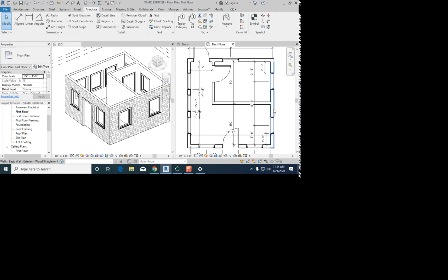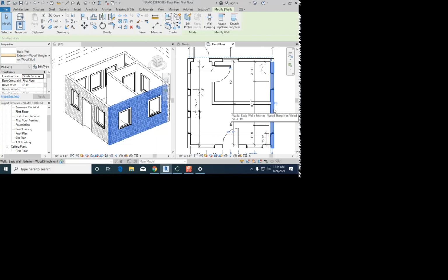Okay. So again, just like a window, grab the wall you want to move and then change the dimension. Don't just click on the dimension and try to change that. Click on what you want to move. Do I just click save the project when it asks me to? Yeah, or the shortcut is Control S. I neurotically hit Control S at many intervals.